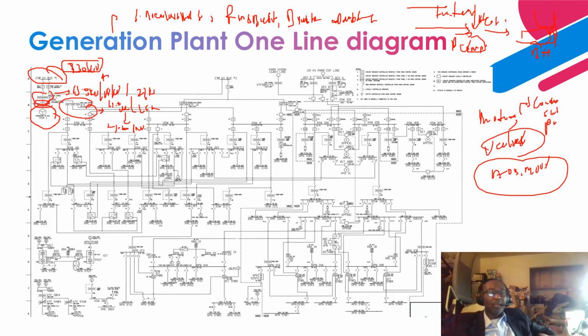So that is why you are utilizing a 3-winding transformer, to be able to achieve many different medium voltage buses that can provide power, right? So you are able to step the voltage down utilizing this 3-winding transformer to 4.16 kV and achieve many medium voltage buses out of that.